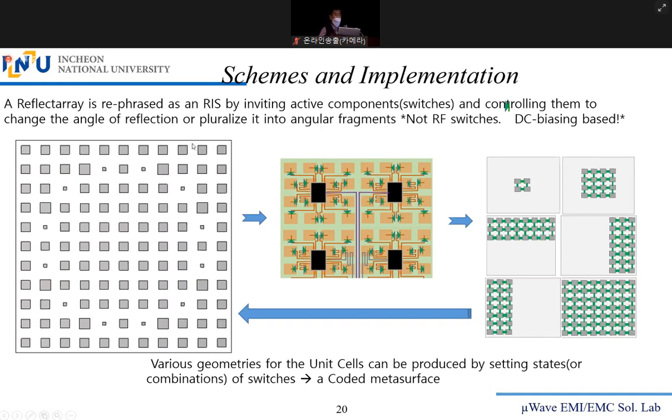And if we take a 2x2 or 4x4 subarray, if we open the material that is backing the structure, you can see all the switches. Can you see that? PIN diodes. So these PIN diodes are driven by the chipsets.